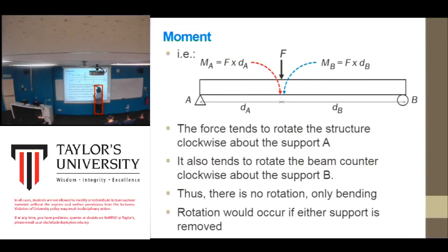Can or not? Do you guys understand? Moment. This is moment. My hand is a support. So when the pointer moves, this is moment. We call it moment. It can be in the form of clockwise or anti-clockwise. Here I didn't mention, but as Mr. Adib said, the convention that follows is clockwise is positive, anti-clockwise is negative.